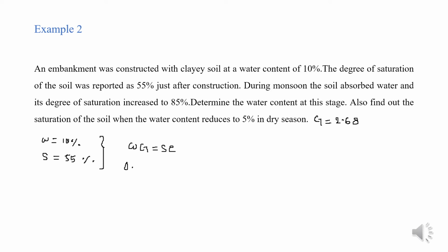Water content is 10%, G is 2.68, the saturation comes in the denominator, it's 55%, and we can get the void ratio of the sample.